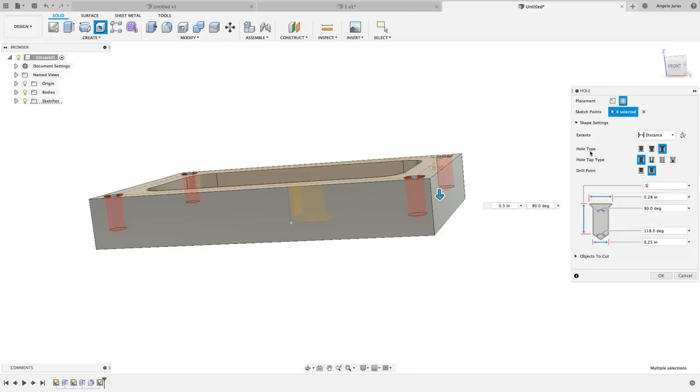And a couple of things here on the hole type. You can create a simple hole, a counterbore hole, or a countersink hole. I call it countersunk hole. And then the depth we've got defined is 1/2 inch. The countersink, I'm going to call it, because the hole is going to be 1/4 inch, and I want a nice 30 thousandths or 15 thousandths per side chamfer.